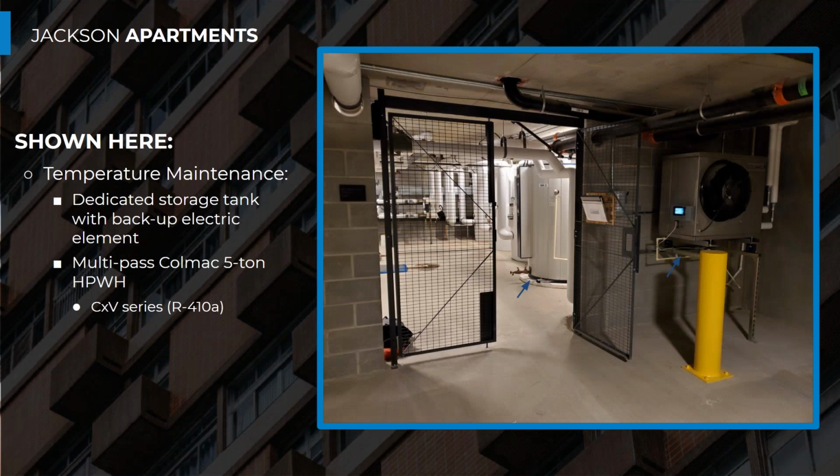If we can get these heat pumps a good distance from that garage door that's letting cars in and out of the garage, and a floor down in the building, we definitely see very steady temperatures, typically above 43 or 45 degrees Fahrenheit. If it's closer to that door, that's where we see more seasonal impacts for that ambient air temperature. Got it. Makes sense.